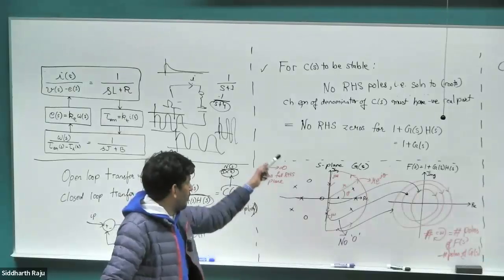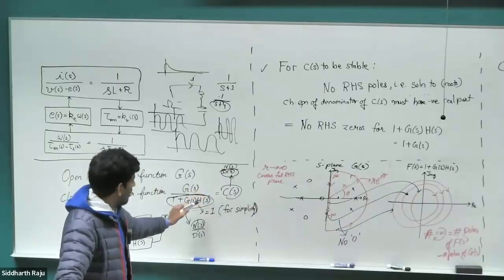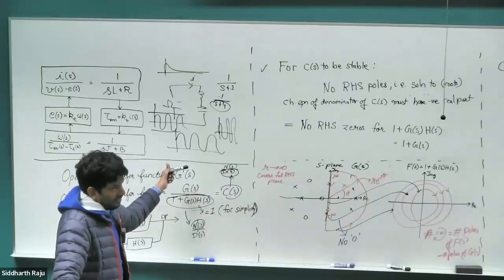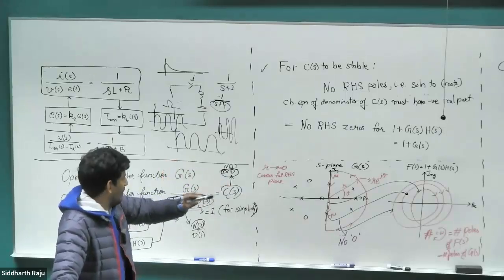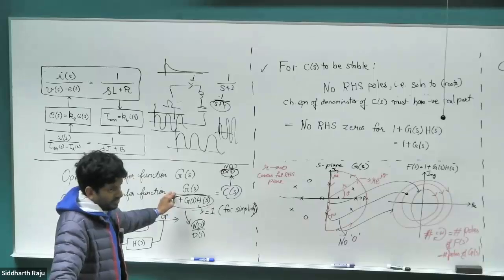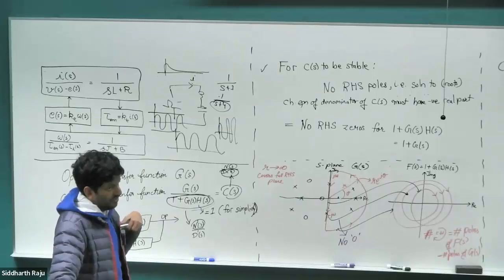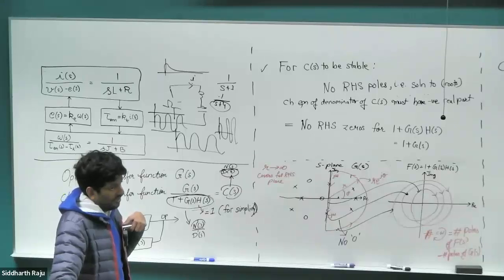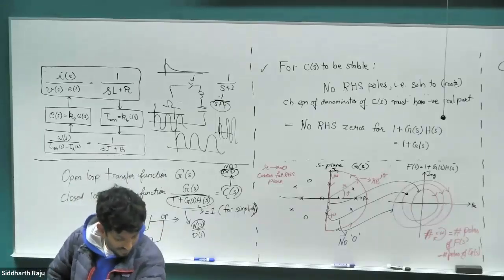Oh, we would. If you evaluated the S-plane for the closed loop transfer function, and you find the poles of it, then you can quite easily say whether it's stable or unstable. But the advantage of going the Nyquist route is that you don't need to look at the closed loop transfer function at all. Just by looking at the open loop transfer function, I can immediately say whether a system is stable or unstable. If you just look at the open loop though, isn't there some element of the 1 plus G(s)H(s) that it wouldn't show you? Like if this was stable, you would still have to check.